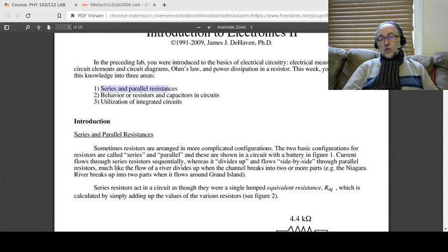Then we're also going to look at a new electronic component called a capacitor, and we're going to put a capacitor in series with a resistor, and that leads to a timing circuit. This is a very important circuit, even in biology, because a lot of things in the human body act like RC circuits, where there's both a capacitance, which I have yet to introduce to you, and a resistance, and potential, that is voltage in the human body, is simply produced chemically.